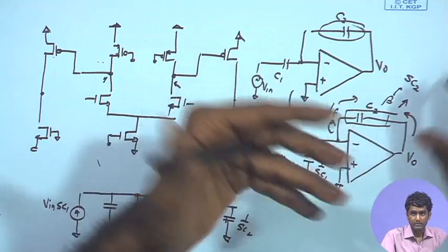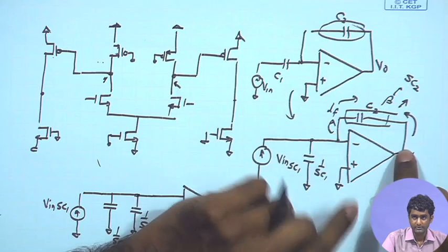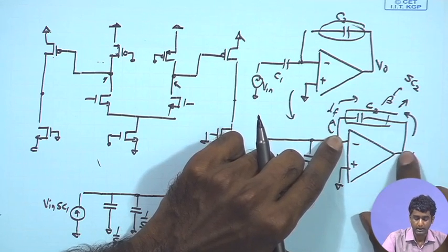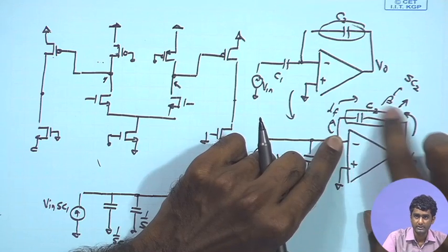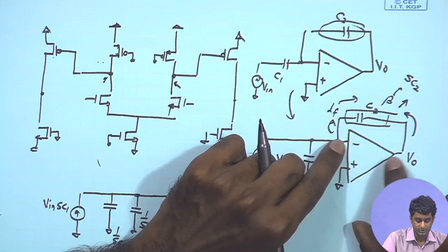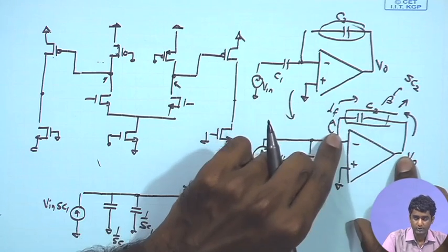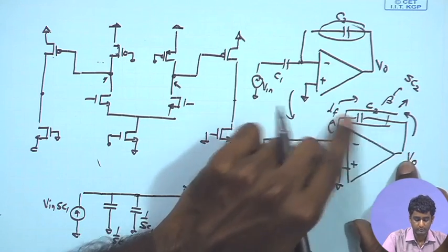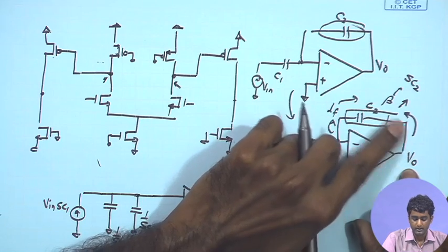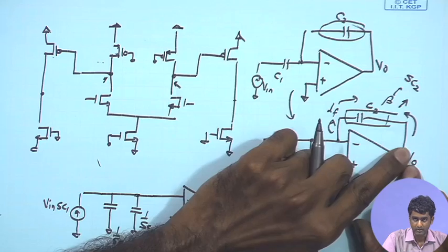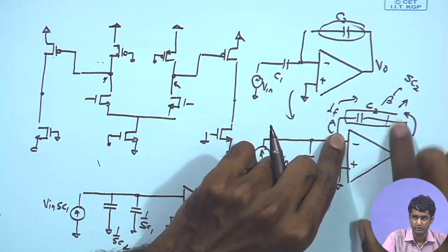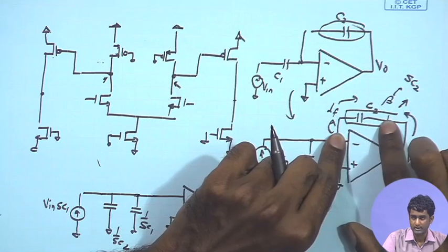Remember, in order to find out the feedback factor for the shunt case, we need to put a ground at the output port of the feedback network, apply a voltage signal over here, and then see what is the resulting current. Why do we put a ground at the shunt connection? Because remember, this is acting like a voltage to current converter. So, this feedback network is sensing voltage and providing you current. As a result, we are trying to estimate the gain, basically voltage to current conversion factor for this voltage to current converter element.